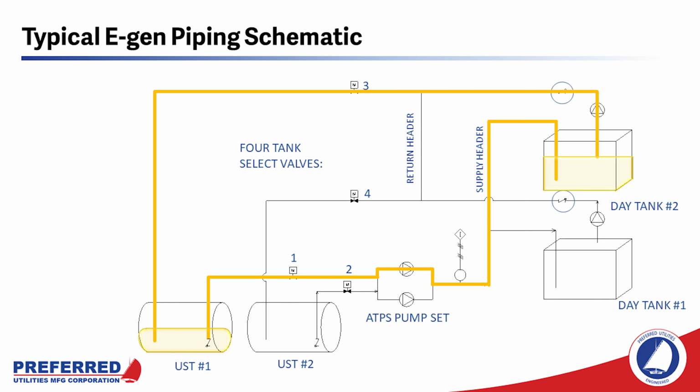So I just would like to add on the return pumps. Sometimes we'll get some hesitancy by design engineers to add a return pump to a system if it's a mission critical application, and they see that as a possible point of failure for fuel to be removed from the tank. Some of the ways we can handle that, we can put a drop tube on that return pump that only goes down to about 40% of the tank. So around 40 or 50% is typically where we would have our low alarm point. And that'll allow us to fully test the level sensor in that storage tank, but not allow the return pump to pull it down unnecessarily low or starve the tank if there was some sort of controls malfunction.